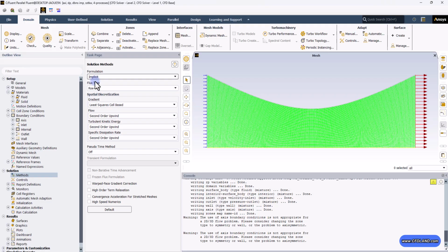So there are two solvers in Fluent when it comes to this. And the density-based solver is much better and more accurate because density and energy are tightly coupled. And for this, we're going to use the implicit Roe-FDS flux type. This is a specific mathematical scheme used to calculate how waves like shock waves travel through the fluid. It is very accurate for shock waves inside the nozzle.